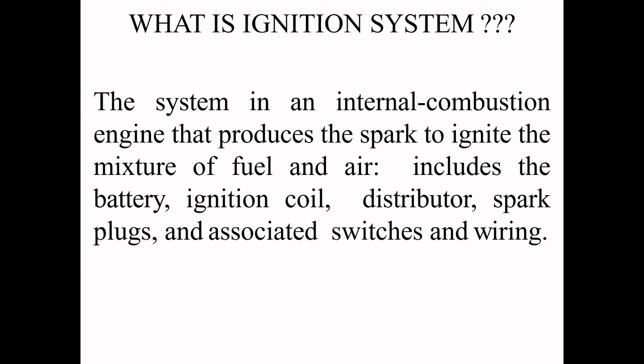Let me give a brief description of how the petrol engine works. During the suction process, a proportionate mixture of petrol and air is inducted into the engine cylinder from the carburetor through the open inlet valve.